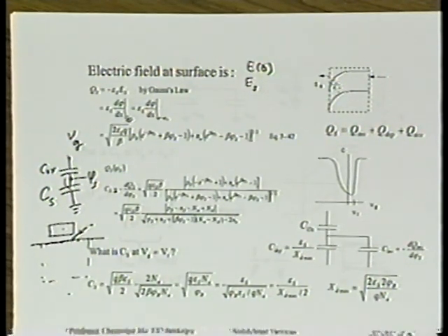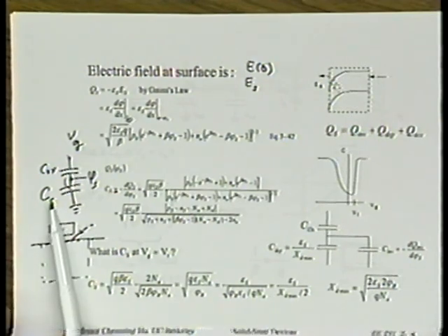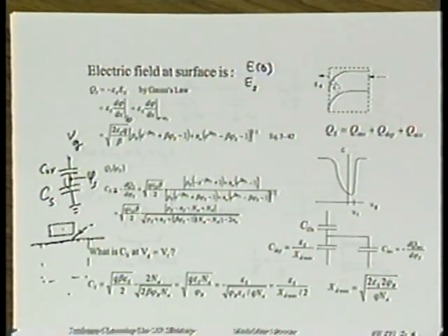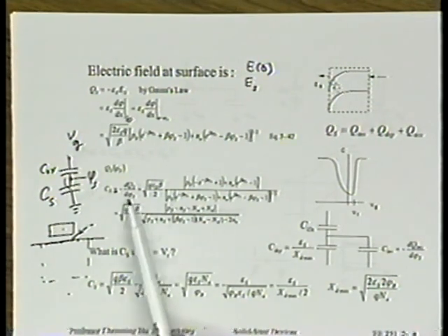So dQs/dφs is the substrate capacitance. That's probably a new term for you. So let's agree to call this capacitance the substrate capacitance, CS. All right? Okay? Don't think we're just representing the depletion layer capacitance. Not at all. This is going to represent the inversion charge capacitance, and the accumulation charge capacitance. Can you agree with this idea?